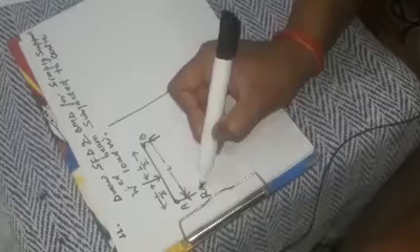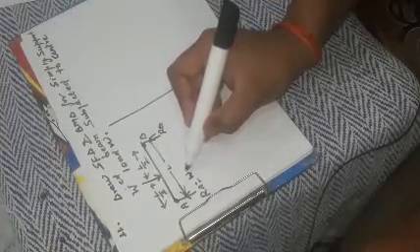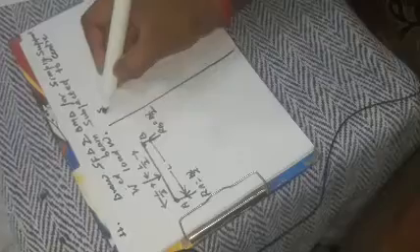Then here will be reaction A and here B, RA and RB, and value of RA will be, for this case, W by 2, and here it will be W by 2. So this is actual loading diagram, now it is completed. This is the loading diagram of given problem, right? Now we will calculate the shear force value for this problem.